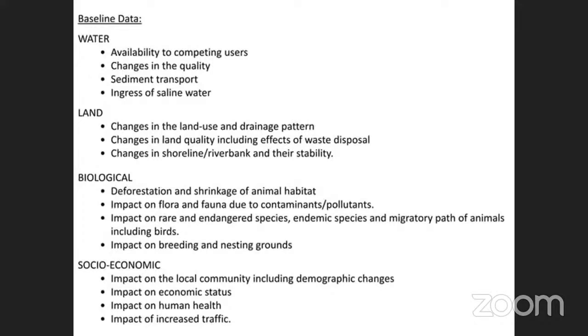And groundwater assessment. The groundwater samples are also collected from feasible locations, because if bore wells or open wells are available, we can easily collect the groundwater samples. Otherwise, it may be difficult to collect the samples. Depending on the availability of sampling locations, we select the locations, collect the water samples, and analyze them in the enabled laboratories, the data required for the EIA.